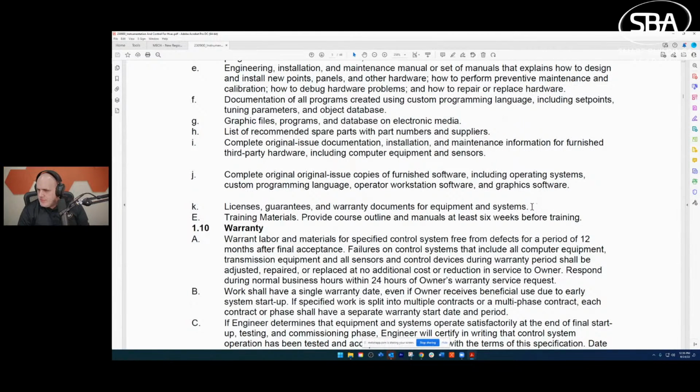What do you do if you see specs that have DDC points lists? I'm reading a spec with a ton of points lists and it's great. So therein lies the question. Is it a representative points list or is it a standard? So like I refer a lot of people to the Northwestern University Building Automation Standard. I think it's one of the better ones out there. It's grown a lot over the years. It's really nice. They get into points list, point naming, graphic standards, etc.